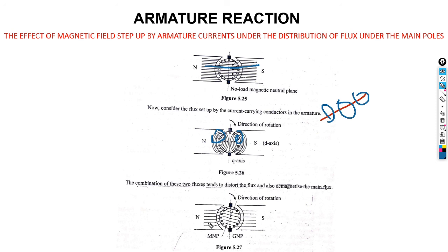The flux wants to be straight, as it shows from the beginning here. We're going to have a distortion of flux. The flux will move a bit like that. So this can damage our generator. In order for our generator to operate well, we need to do the correction of our armature reaction. How do we correct the armature reaction?